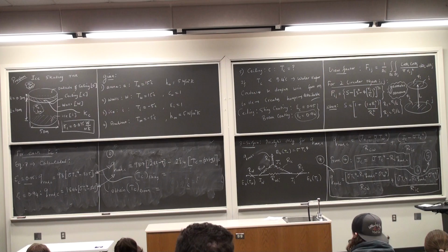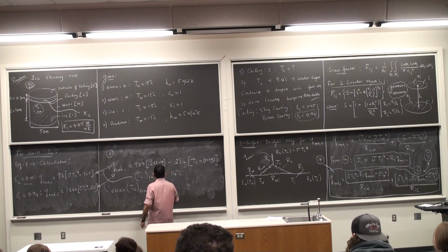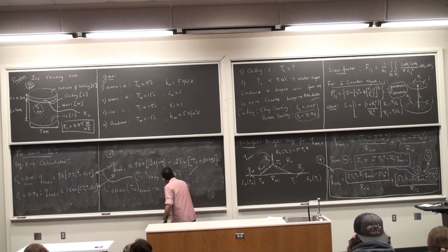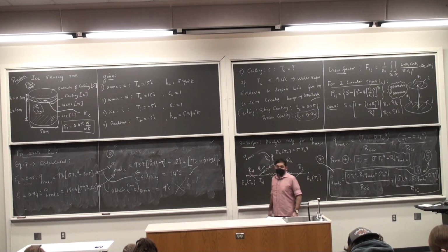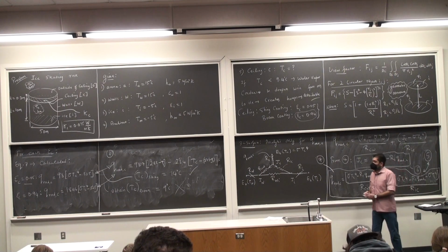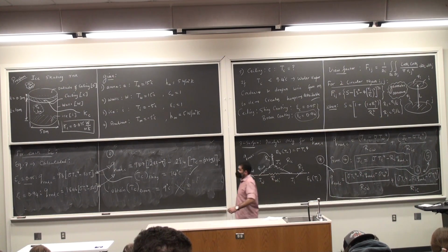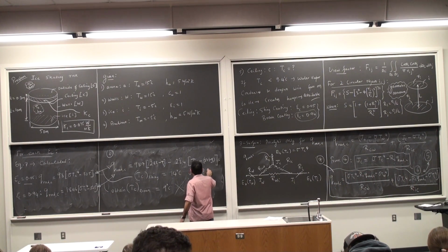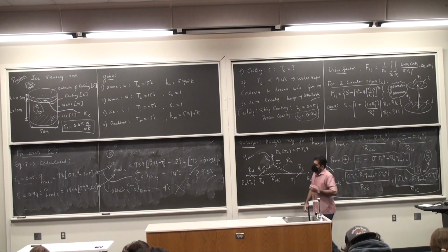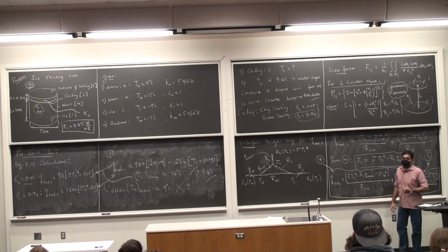The shiny coating will give you a higher temperature because there is lesser heat removed from radiation. Which is why if you go to an ice rink, the top surface is typically shiny. Okay, so this is the temperature that we need because we need our temperature to be greater than 9.4 degrees Celsius.